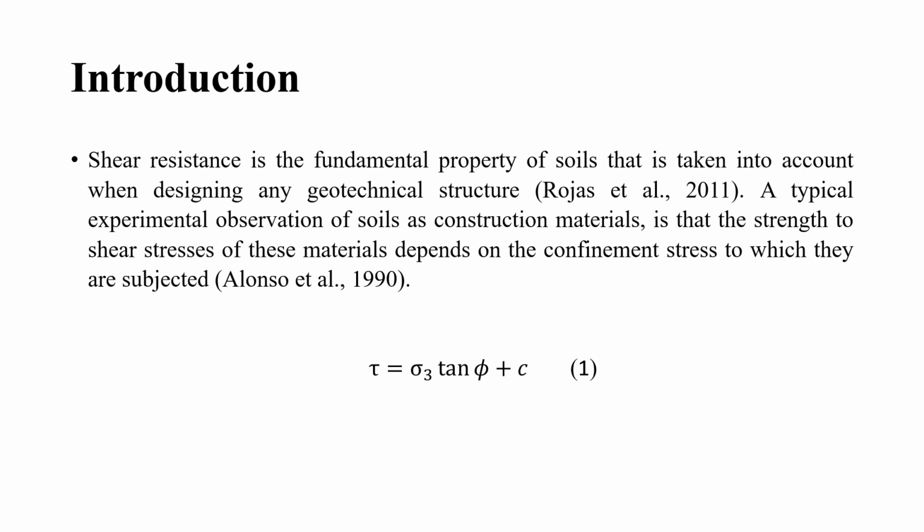The parameters phi and C depend on the type of soil, the drainage condition, and several situations to which the soil is going to be subjected. The recommendation is that we determine those parameters once we subject the soil to the conditions that it is going to face. Only under those conditions will we be able to obtain good parameters for predicting what we want to predict.